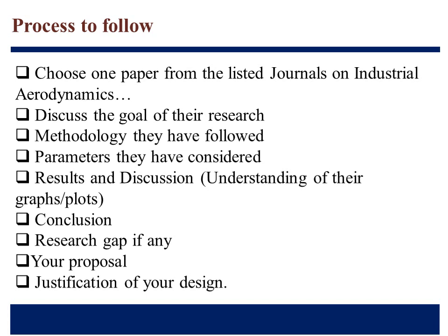Say, in this case, the parameters are the surface pressure, the coefficient of drag, coefficient of lift, the separation point, and then, if possible, you can go through the signals and you can calculate the spectrum, and that spectral characteristics will give the shedding frequency.